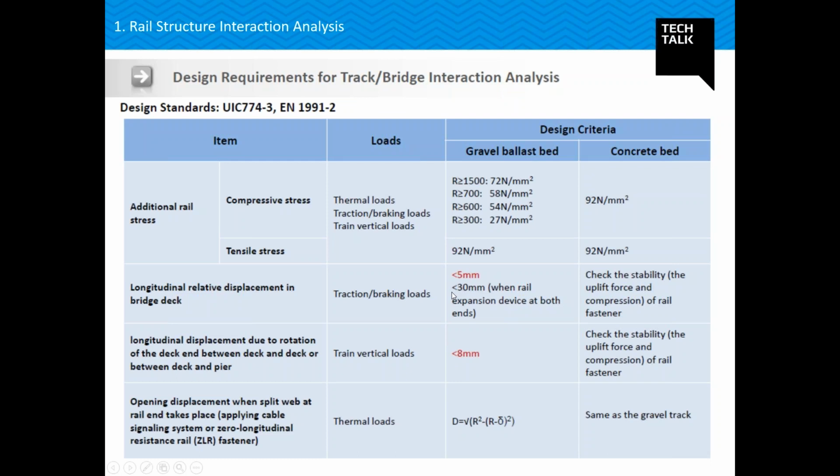If the stability of my ballast is breached, the connection between my rail and deck is disturbed. So I need to ensure the limit state of strength of my rail, and also take care of the serviceability criteria. These are the two things we are checking. First is the stress in the rail. Second is the serviceability criteria between deck and rail. Moving on.